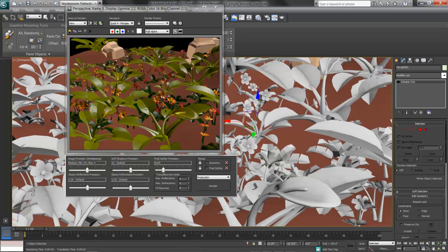We have a lot of options in the materials. In this case, I wanted very translucent plants, so that when we navigate around the jungle, there's a glow to everything, sort of. I also wanted in here some variation, but to economize on the materials I'm using. And I did this by using a texture sheet. And like I said, we'll do this in games quite a lot, where we have one texture sheet in multiple shaders in more materials, either in 3ds Max or the game engine, and we reuse and reuse and reuse that one texture, saving on memory and keeping the frame rate up.